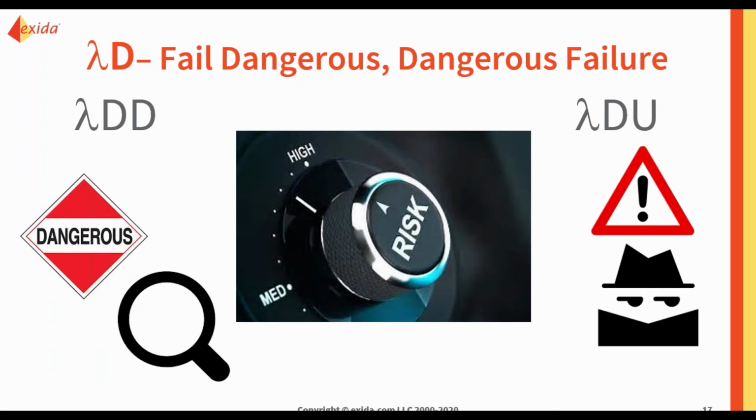So what are some examples of some dangerous failures? Once again, depending on your diagnostics, these could be dangerous detected or dangerous undetected. So for example, you could have a ball valve, and if the valve stem is sheared from the ball, you could think you are moving the actuator, and you think you're moving the ball, but in reality, the ball isn't moving and cannot shut the valve in time. Or you have a solenoid signal and it's not alerting the actuator that something needs to change.